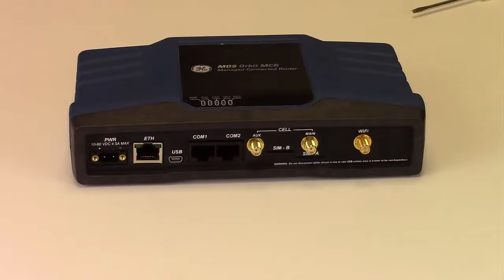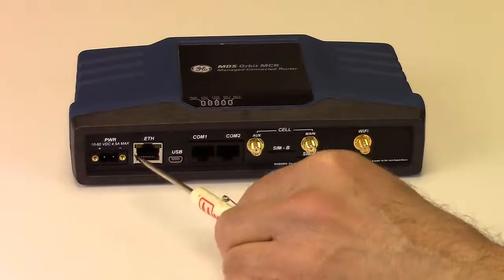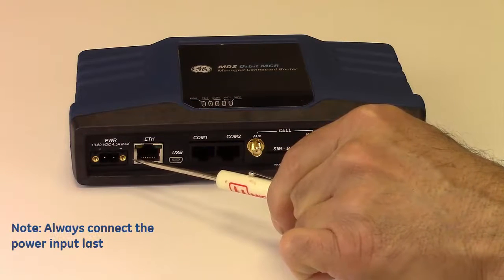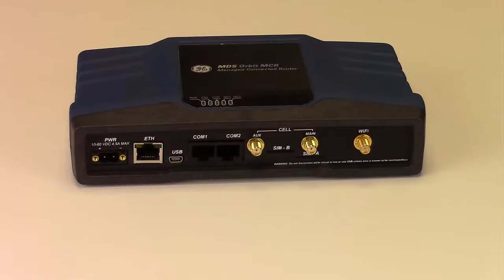In this example, we'll demonstrate by making connections to an Orbit MCR. The exact connector layout will vary depending on order requirements. Starting from the left and working right, we have the power connector. We'll hold off connecting this until the other connections are made. The power input to the unit is 10 to 60 volts DC at a maximum current of 4.5 amperes.